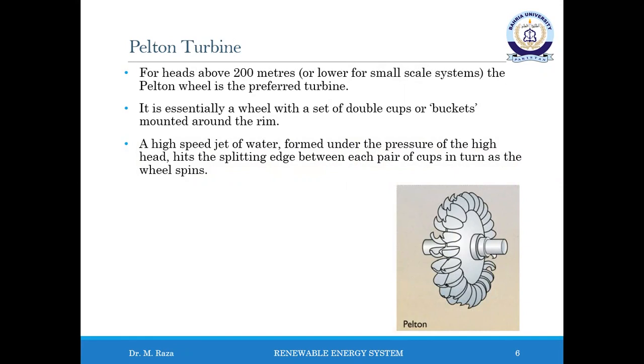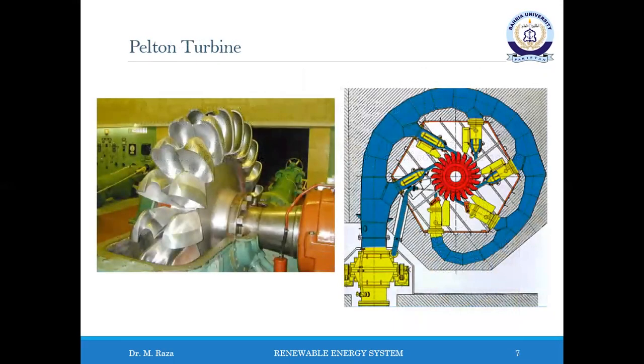The cross-flow turbine has a drum-like rotor with a solid disc at each end and gutter-shaped slats joining the two discs. Water flows transversely through the turbine, entering at the edge and emerging on the opposite side, thereby generating additional energy. The water passes around the curved bowl and, under optimum conditions, gives up almost all its kinetic energy, as shown over here.